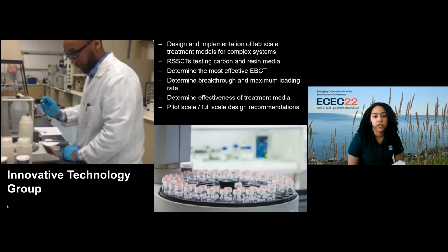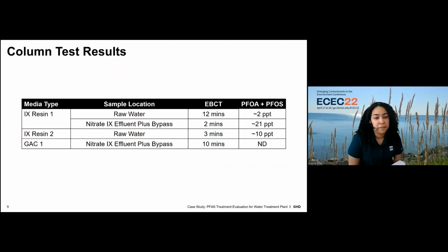And their job was essentially to determine which was the most effective empty bed contact time, the breakthrough and maximum loading, and determine the effectiveness of the treatment media, as well as provide recommendations based on the results achieved. All that work, which took several months, led to what you see here, which is that resin 1, 2, and 3 had the following empty bed contact times with the following results with PFOA and PFAS in combination.